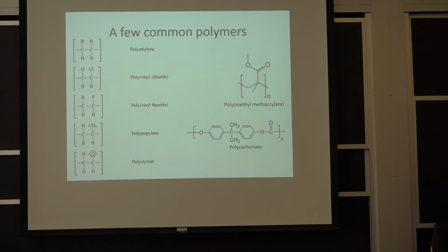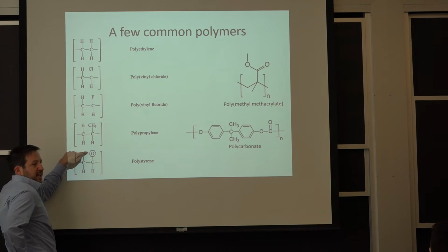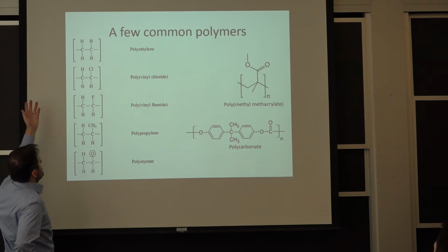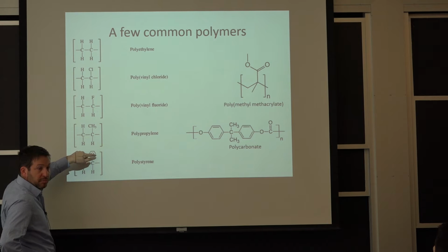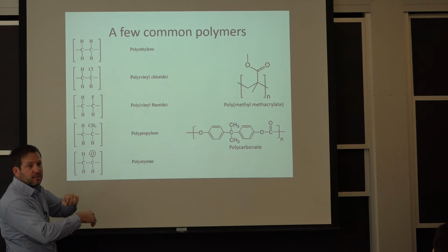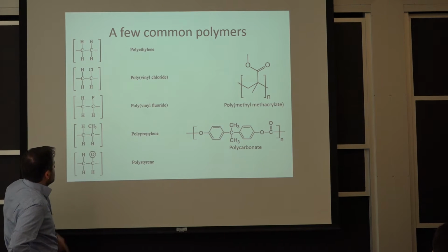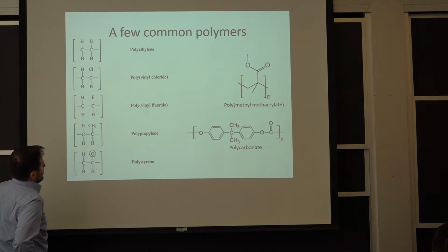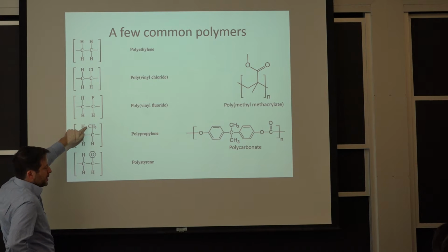So the main difference when you go from a polyethylene to polystyrene, which doesn't have too much deformability, is the size of that side group that is not on the main chain of the polymer. So polyethylene, it's just hydrogen that is on the side. Over here, you have an entire benzene group. That's pretty hard if you try to slide two chains relative to each other. That's a network of 6 other carbons here trying to prevent that from going on. So in between, you have all sorts of combinations. So the polypropylene's got 1 carbon to the side here. Yeah, so that makes a difference.